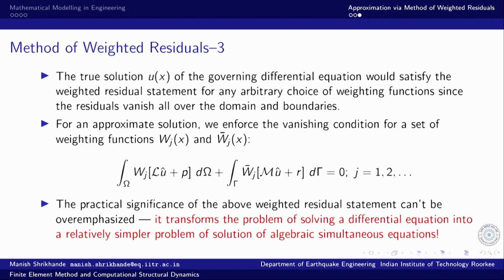So, it remains an approximation, but one that approaches the true solution, as the number of weighting functions for which this statement holds increases, improving the quality of approximation. As I said, the true solution of the governing differential equation would satisfy the weighted residual statement for any arbitrary choice of weighting functions, since the residuals vanish all over the domain and the boundaries.